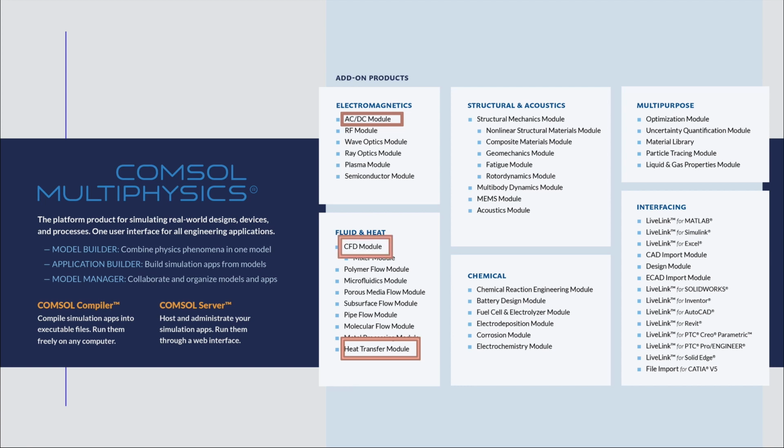And you can also include the CFD Module. So if you need to add some active cooling onto your model, that's also possible using the CFD Module. And we are dealing with rotating machinery, sometimes high-speed machines. Then you can extend the capabilities of your AC/DC Module with the Rotor Dynamics Module. From the software side, in COMSOL, you can combine and couple any number of physics into true multiphysics applications. And these motors and generators, yes, they are true multiphysics applications.